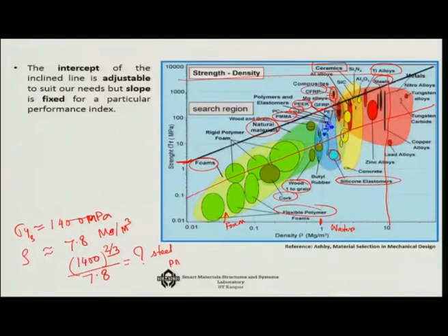And for PMMA, if you do the same thing, the maximum value if we take for PMMA is somewhere like 40, so 40 to the power 2/3, and density-wise, it is close to water, so it is about something like 1.2, maybe 0.6 in the scale here.